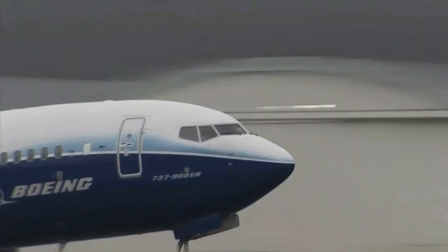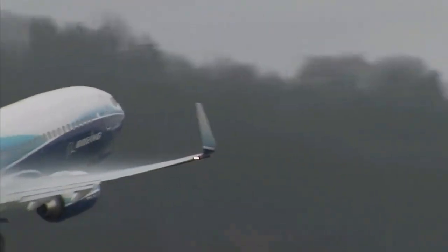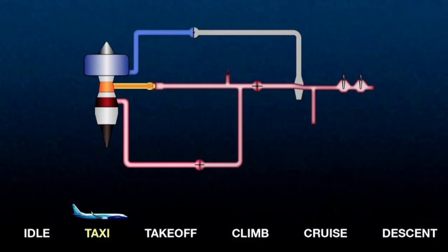At ground idle, once the engine speed is low, the HSV is open and the system is running on the 9th stage air. At these low pressures, the PRSOV is also wide open. The temperature is usually low enough that the PCCV is closed. At taxi, the high stage system continues to supply the bleed air.